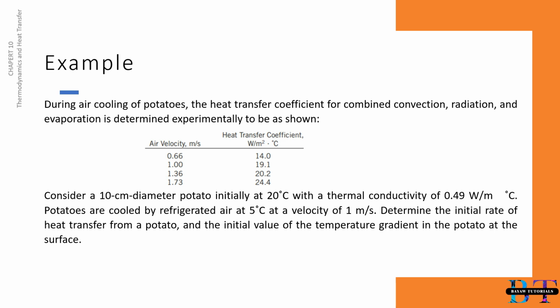So first, let us identify the givens in our example. We have the diameter equal to 10 centimeters. Our temperature of the surface is equal to 20 degrees Celsius. Our temperature of the fluid sufficiently far from the surface is equal to 5 degrees Celsius.